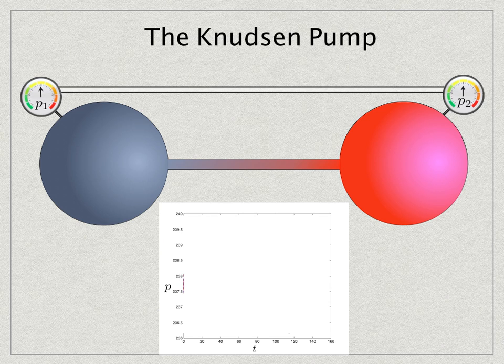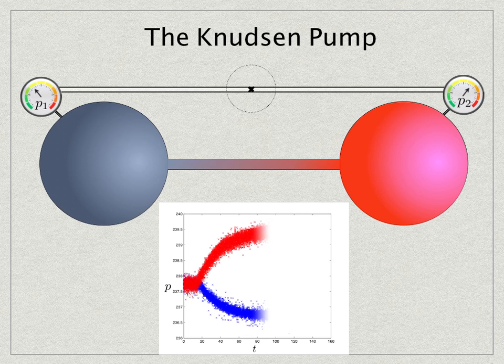That creates a thermal transpiration flow, and then at some point in time they close the valve that connects the two reservoirs, and the pressures then diverge and then go to a steady state, and the pressure in the hot reservoir is higher than that in the cold reservoir. And the reason those pressures aren't symmetrical is because the two volumes aren't actually the same in their experiments. So that's the actual experimental data.